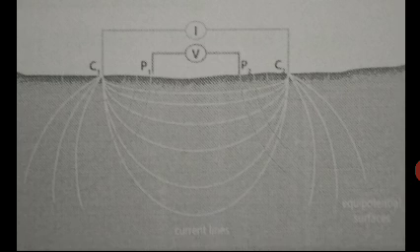Resistivity, the inverse of electrical conductivity, is a measure of the capacity of a rock to allow an electric current through it. Dry rocks and sediments, dense, compact, and non-porous rocks will offer a greater resistance to the electric current compared to loose, porous, and wet saturated materials.